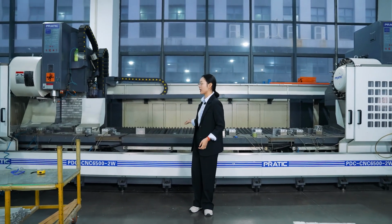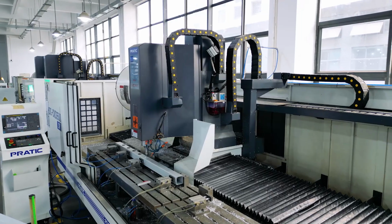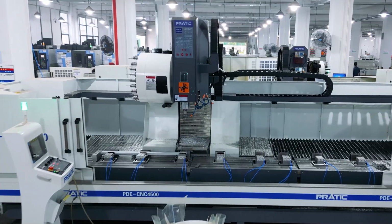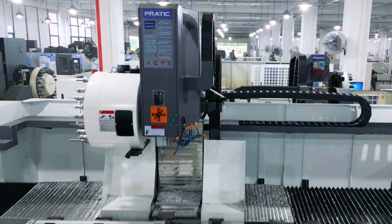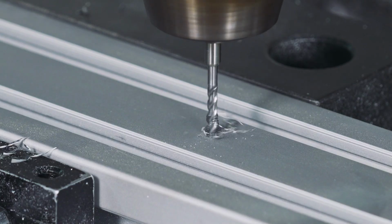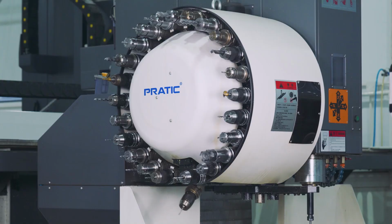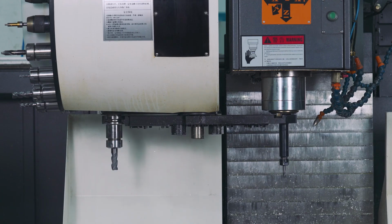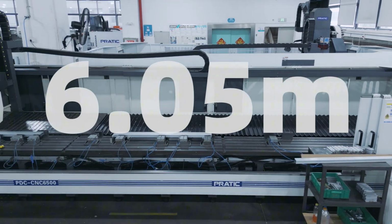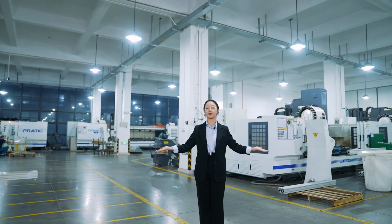This is a customer-designed aluminum profile compound machining center. It features 3-axis linkage and can perform precise machining processes, such as milling, drilling, chamfering, and tapping in a single clamping. The machine is equipped with a 24-tool carousel magazine, and the tool change time is only 2 seconds. This one has a machining stroke of 6.05 meters, and we have 9 of them here.